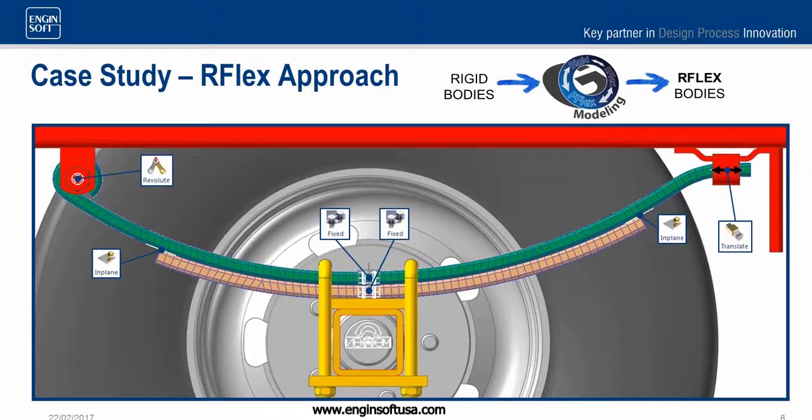I would like to connect the lift spring upper part and the lower part, but I cannot apply a nonlinear contact between the two bodies to connect them. So I have to apply a simplification, and I add two in-plane joints at the ends of the lower part, in order to link the lower part to the upper part. With these two simple supports, when the upper part bends, it will press on the lower part ends.